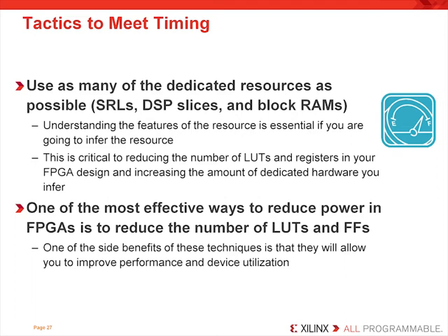One of the side benefits to following these coding techniques is that your design will use less power. That is because your design's power consumption can be optimized by using more of the dedicated hardware resources rather than using LUTs and registers.